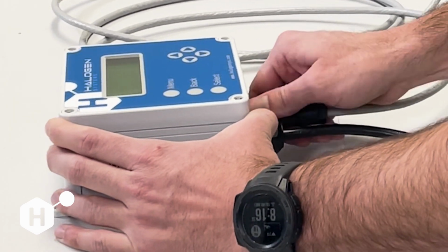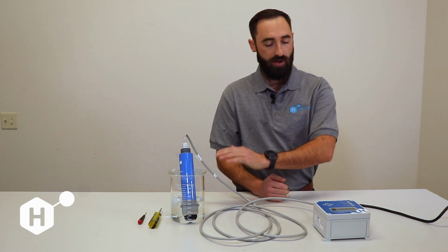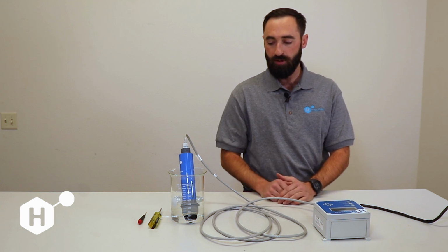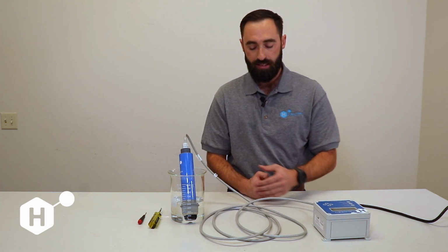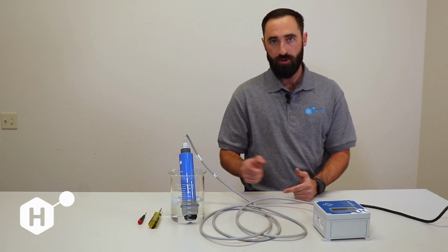When you're having communication issues, one of the things that you really want to pay attention to is whether or not the sensor is powering on. The best way to do that is to troubleshoot any communication issues with your sensor right next to you, somewhere where you can hear it.